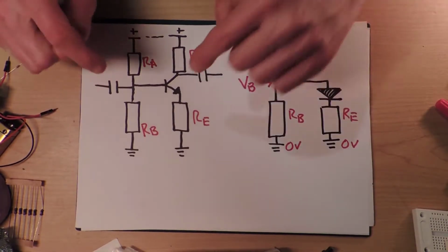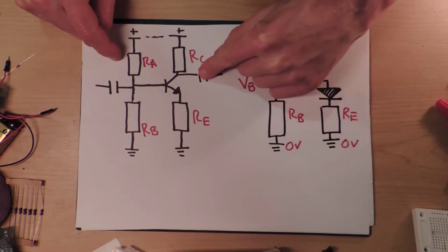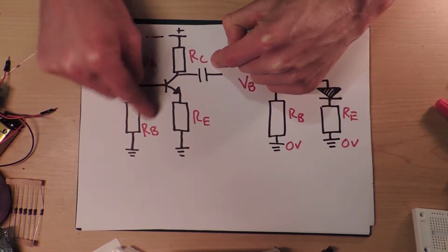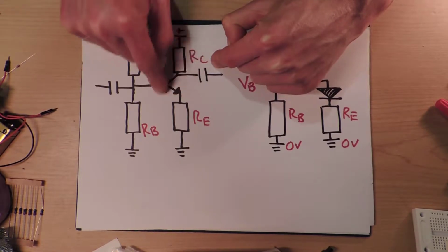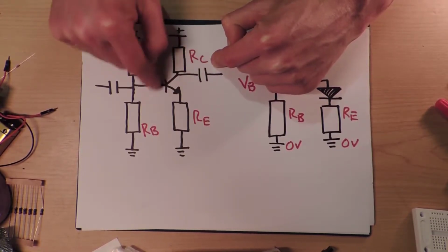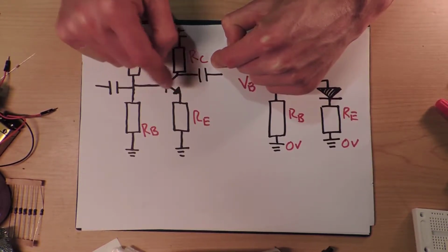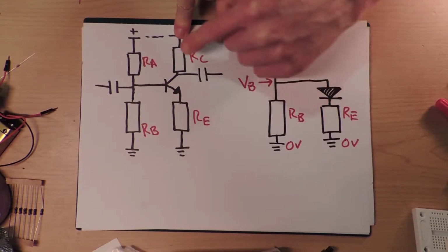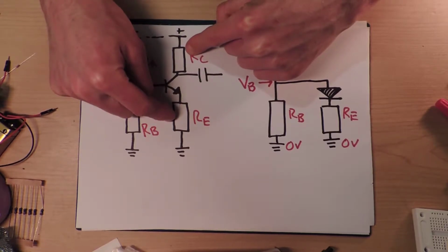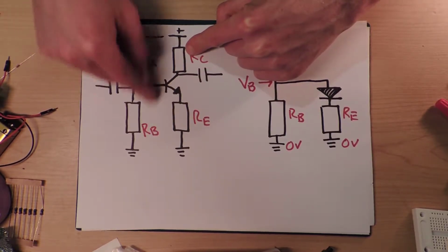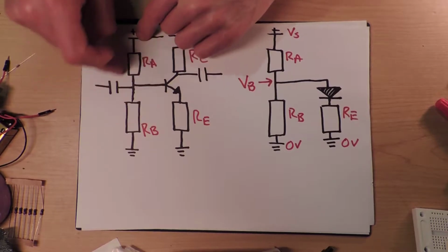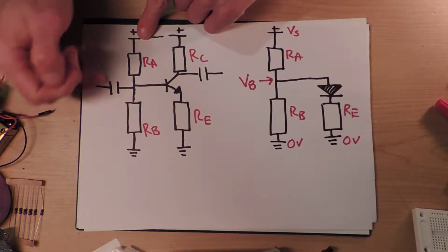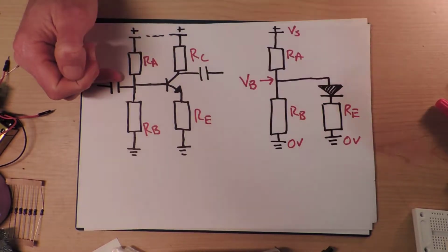But anyway, I've been trying to work out this kind of circuit here. I'm not really going to go into it, but they have the sort of biasing. This is the bipolar junction transistor here, and that's the collector load resistor. That's an emitter load resistor, and this is a biasing circuit. One way of looking at this is like a voltage divider here. This is the input signal coming in here. This is meant to be an amplifier circuit.